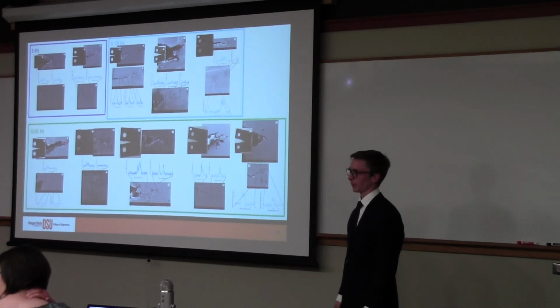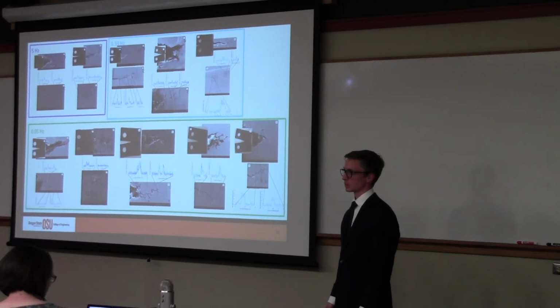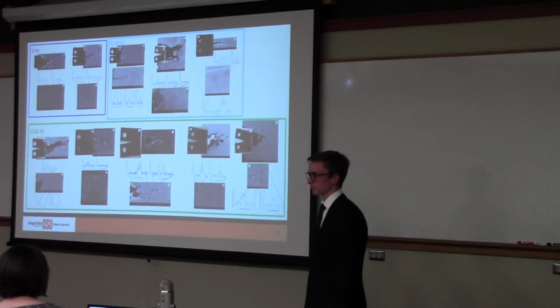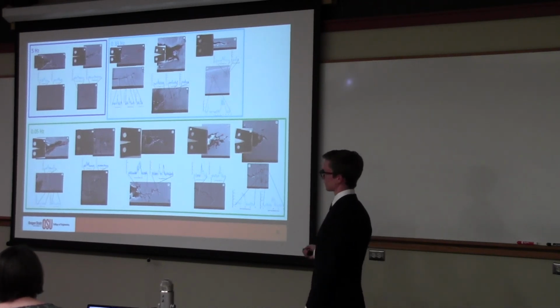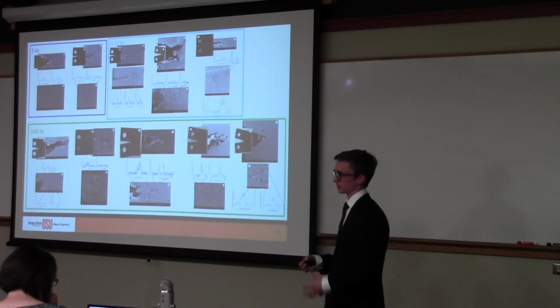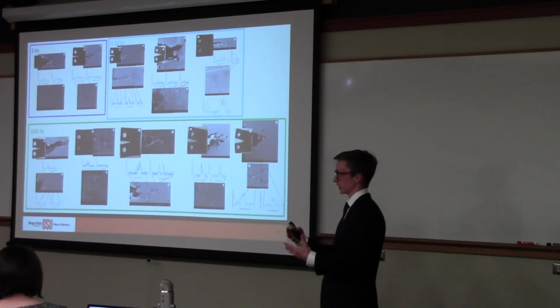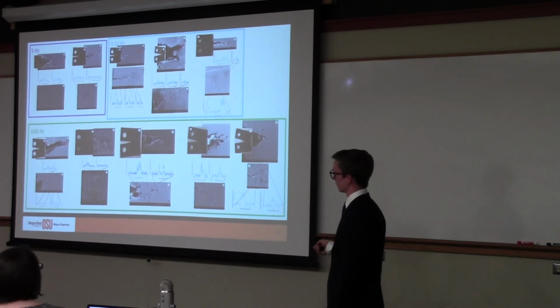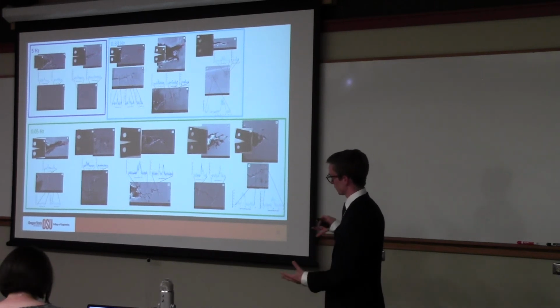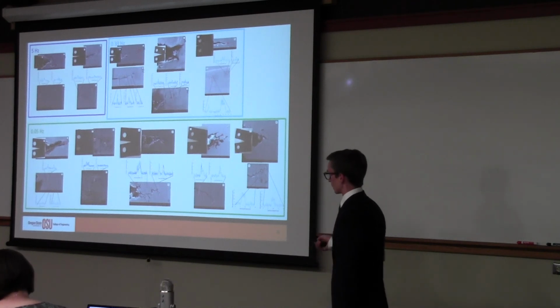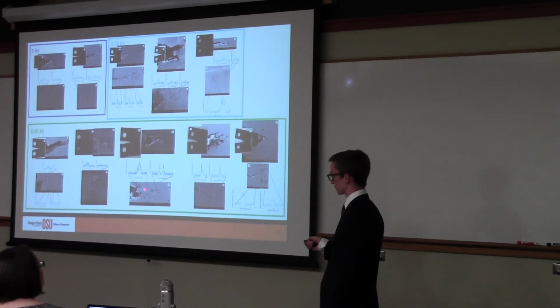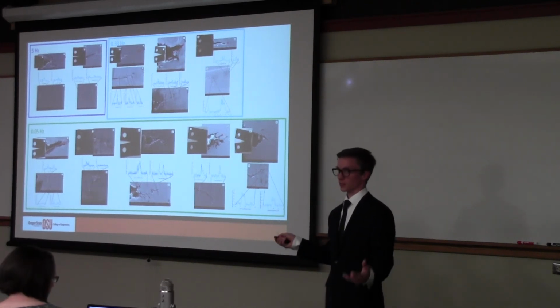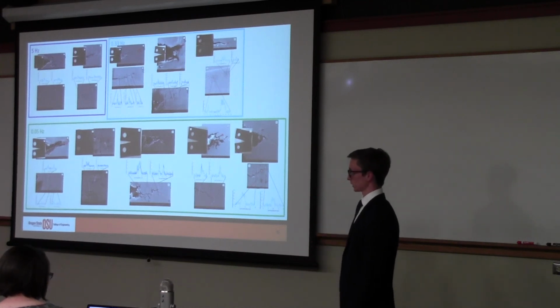I was going to follow up with a question about the oxide. You said there were like 9 elements in this alloy. Do you have any idea what is creating the oxide? Yes, it's chromium, and that's the design of the alloy, that it has a high chromium content so that it forms a chromium oxide, like Cr2O3. If you do a point scan with your EDS system, energy dispersive spectroscopy, you can get the stoichiometry of Cr2O3, and you're fairly certain that's what forms in all the tests that everybody does on this stuff in air. So that's definitely what it is.